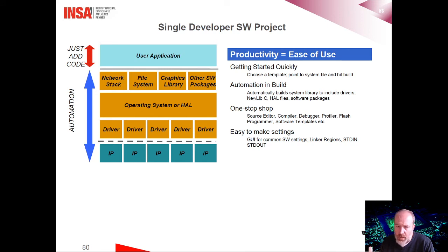Then, all network stacks, file systems, graphics libraries, and software packages are automatically provided by the tool according to the SoPC file that has been generated in QSys, remember? All peripherals come with their drivers, or at least provide helpful tools to develop them.